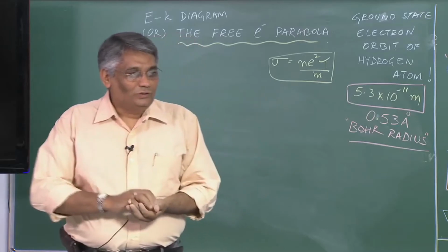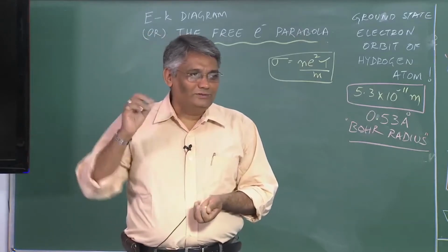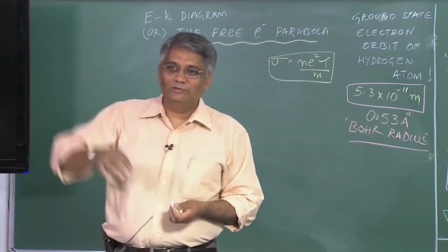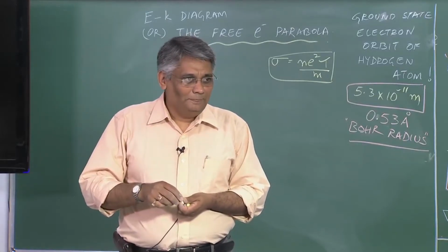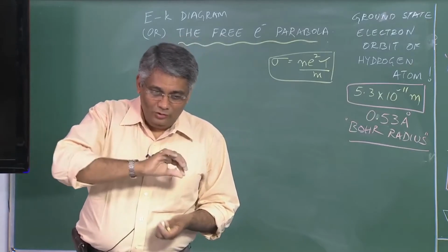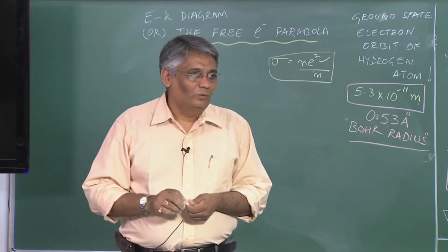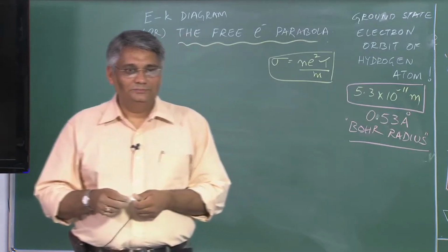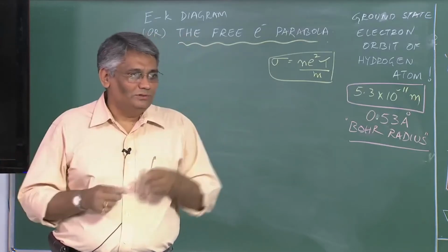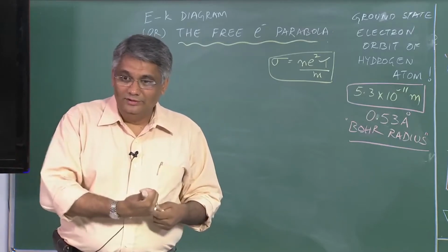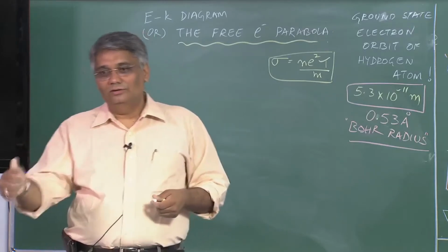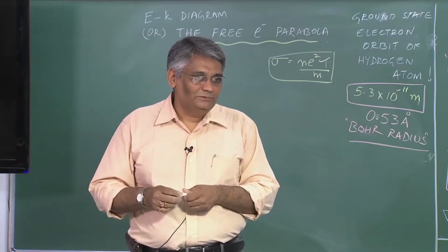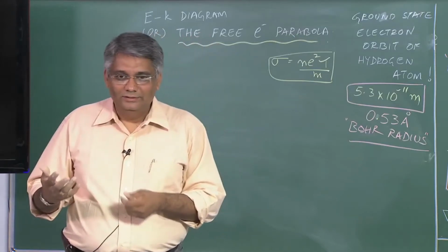So in reality, in a metal, in a conductor where you are supposed to have free electrons, the electron propagation will be there only when you have applied a field in a particular direction. With this random motion, the electrons can drift in the direction or in the direction opposite to the electric field, depending on the charge of the carrier. So that's why we always talk about the drift velocity.